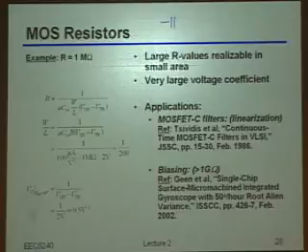So let's just say, for whatever reason, I need to AC couple into the input of my amplifier, which in this case I'm indicating just by a transistor, right? Well, I need some resistor there to set that DC bias. So what are the only things that I really care about from the standpoint of that resistor? In other words, what sets the value that I would want to use there?